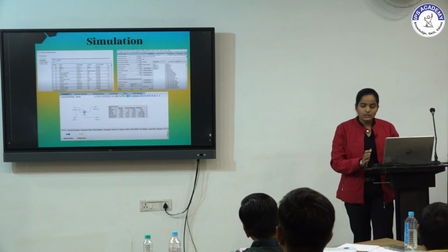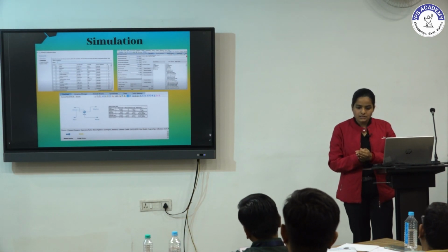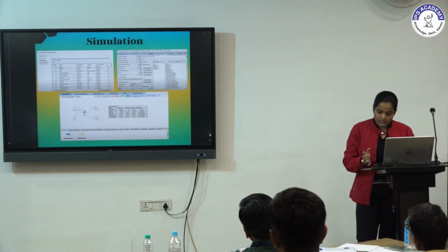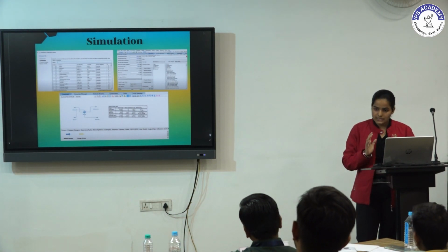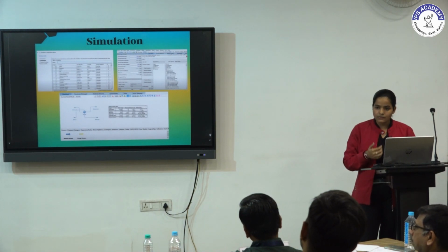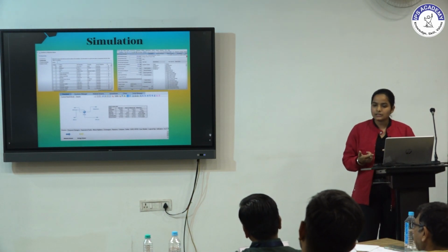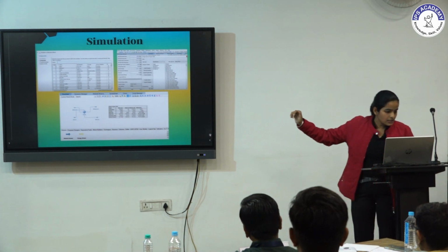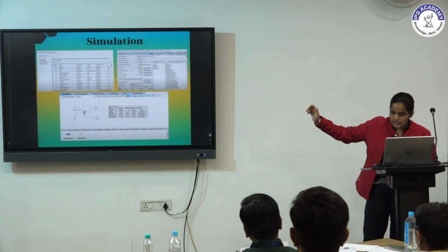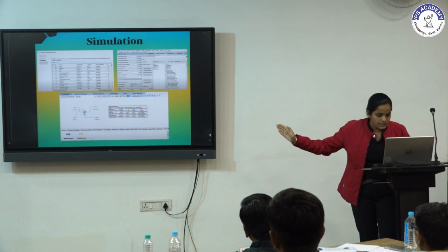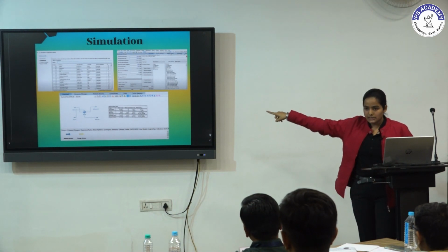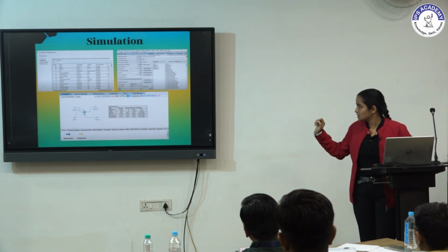So at last, we should navigate to the calculation parameters, and we should select the shell and tube heat exchanger ratings. Then if the flow sheet is ready and all the values are in, we should proceed further with the solutions and click on solve and get our results. So these are the images. The first image is for when we have selected the compounds, and the last image was when we have added all the material streams with the shell and tube heat exchanger.